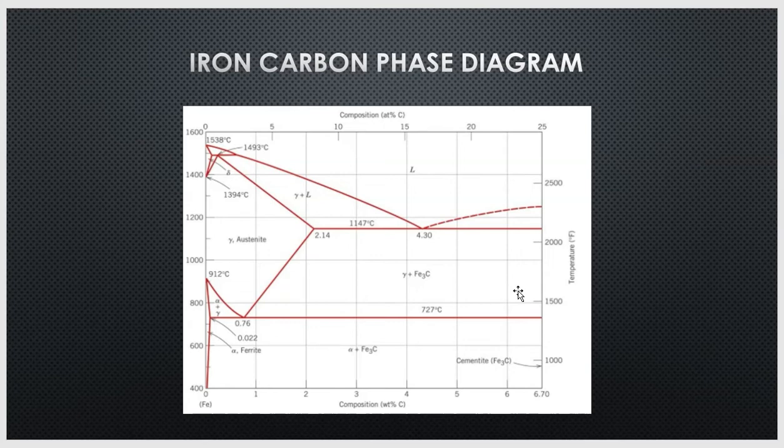And so this comes into play when you have a piece of steel that's at room temperature, and you know that it has not been heat treated already, this is something that's at its normal original state, and you wanted to harden it. Depending on the carbon content, you would be able to tell what temperature you need to bring it to. You would bring it up to the point where that steel is now called austenitic, or basically the steel is no longer magnetic.